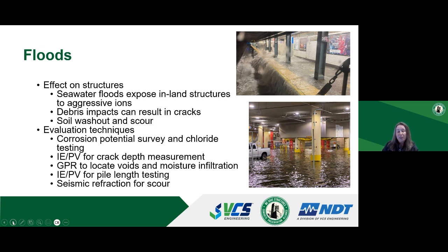Floodwaters sometimes can dislodge large objects that impact structures and cause cracking and spalling. In addition to damage to reinforced concrete, floods also cause soil washout as well as scour, and this can undermine the integrity of the structure.